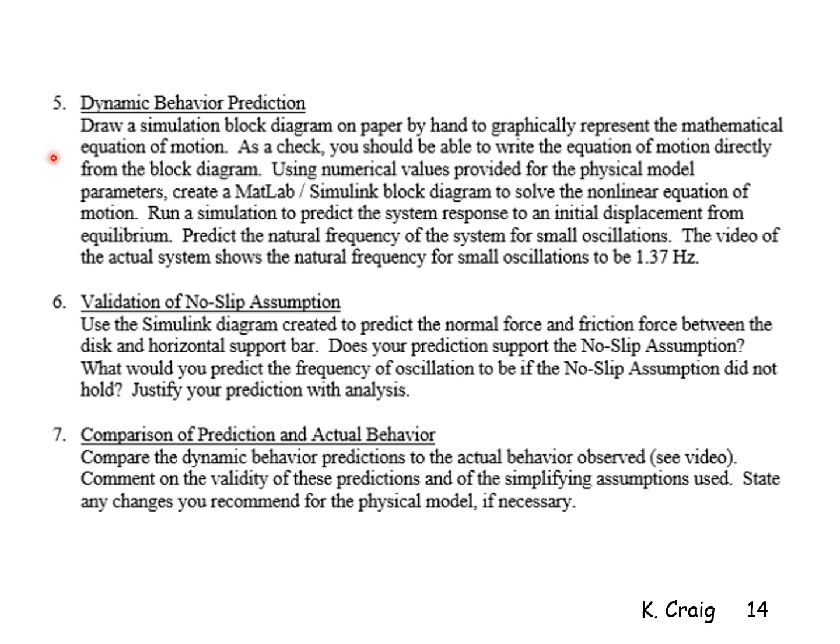You always can test that, and if you get the same differential equation that you started with, then your simulation diagram is correct. It accurately represents the equation of motion. The equation of motion may be wrong, but your simulation diagram accurately represents it. So there is never a reason for an incorrect Simulink diagram in any problem that you solve.